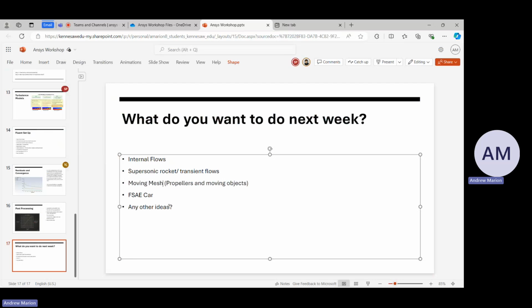Are you trying to do an unstructured mesh right now, or structured? We have Luke over here, he's good with Star-CCM+. But we're trying to figure out Ansys as well, as a backup. We're not in a particular rush, I'm just trying to figure it out. You can maybe try it in Ansys and see if that's easier. I know in Fluent there's the curvature option, and it gets the mesh really tight with the curvature. But it also makes a ton of cells, so you've got to be careful with it. Do you have a computer you run it on?